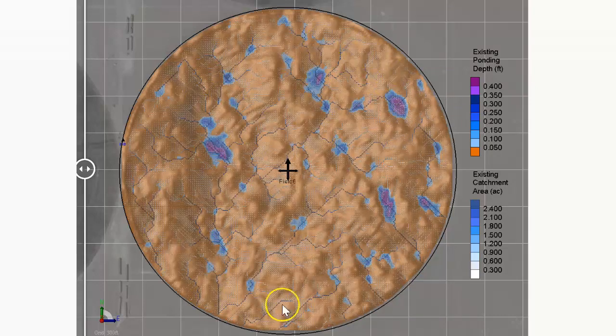The other critical part about center pivots is that you don't want water to run off where you apply it. As the slope increases, you've got more likelihood of water running off, especially around the outside of the center pivot, where the instantaneous application rate from the center pivot is the highest. So OptiSurface landforming has two purposes here. One is to increase the minimum slope so there's no depressions, and reduce the maximum slope to reduce the chance of runoff, and also smooth the field out so that you have more uniform infiltration and machinery operations.